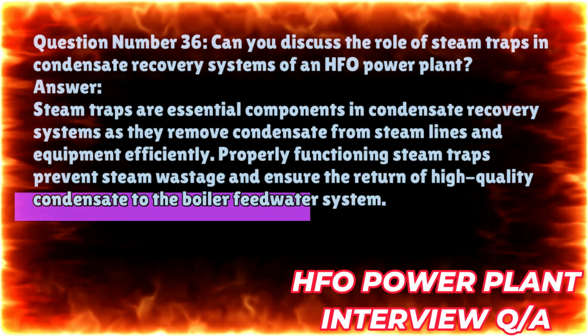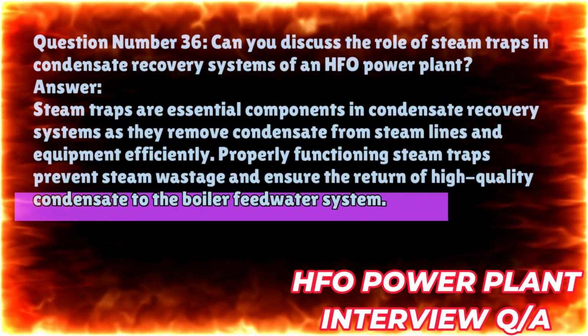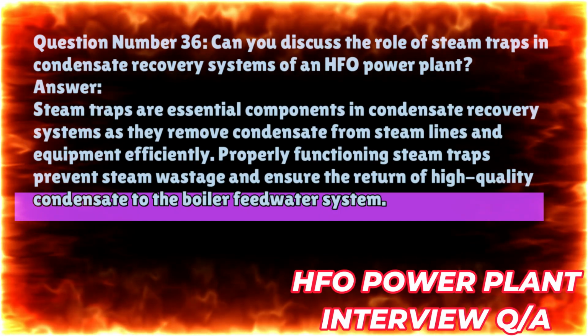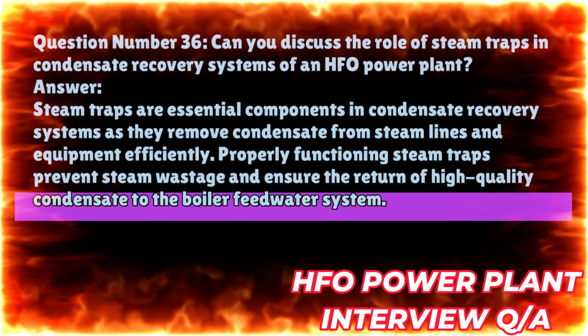Steam traps are essential components in condensate recovery systems as they remove condensate from steam lines and equipment efficiently. Properly functioning steam traps prevent steam wastage and ensure the return of high-quality condensate to the boiler feed water system.